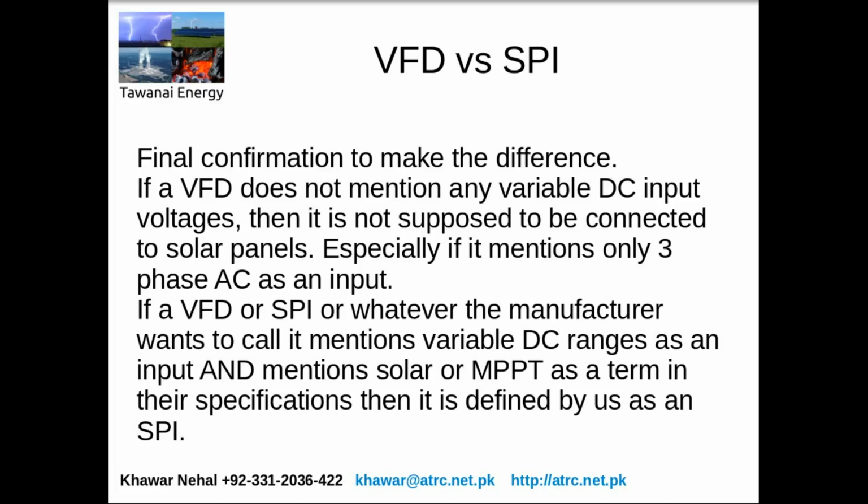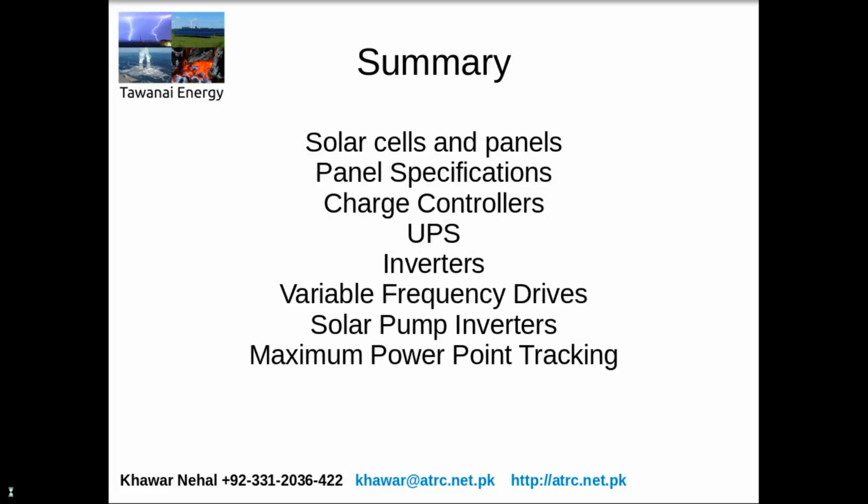And if the input is only defined as 3-phase input or single-phase input, then you can safely assume that it is a real VFD and it's not really designed to have solar panels connected to it, and you run the risk of destroying the VFD if you misuse it.